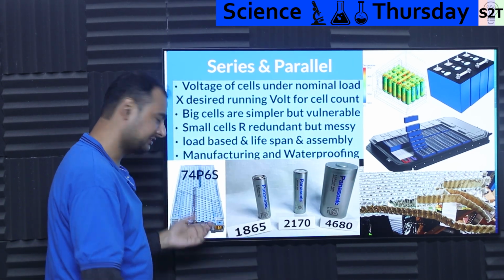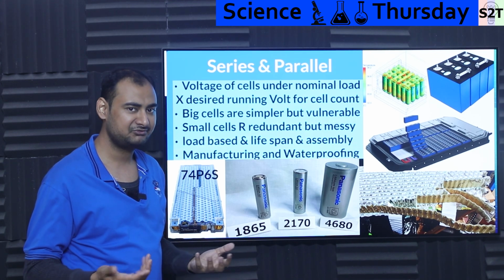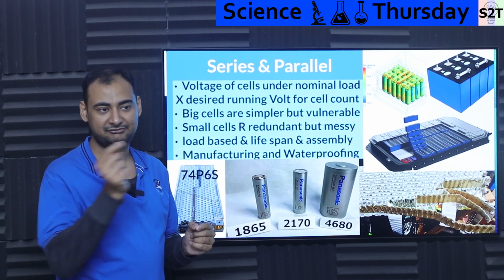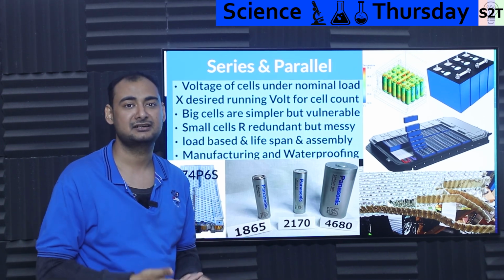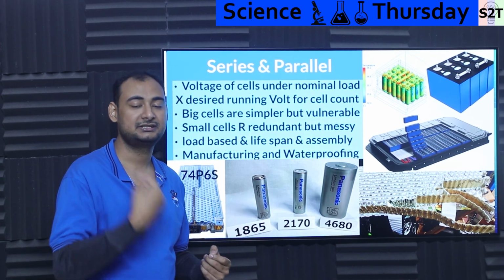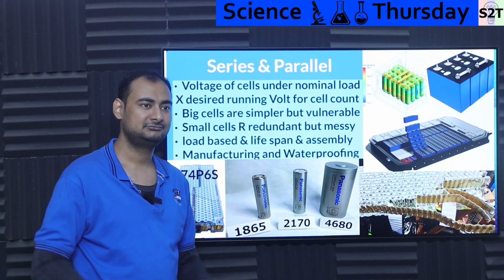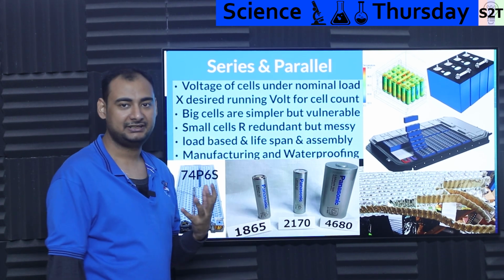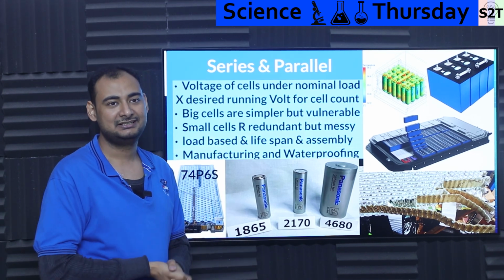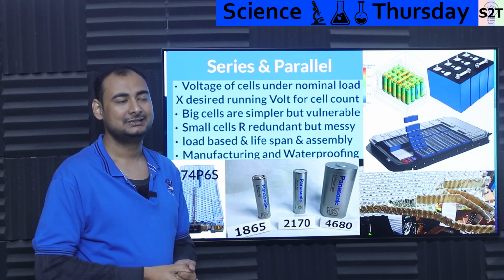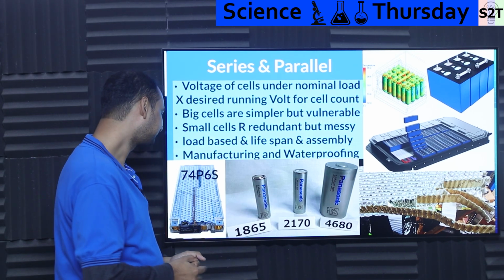Yeah, you can make it. Again, spot welding was a very clever trick. Whoever came up with that, clever. The idea is the fuse wire is the fuse freaking wire. Meaning if one cell, for some reason, let's say its internal resistance drifts too much, it dumps too much current, the fuse wire blows, done, saved. So it's a very inherently safe design. And again, it has resistance. So in the early days, when cells were popping off, it was not frying the whole pack.